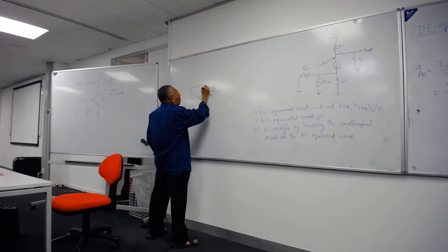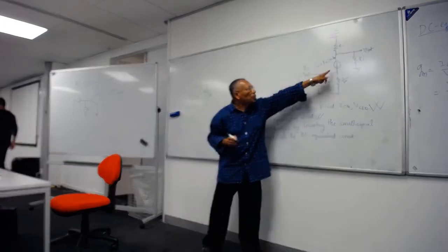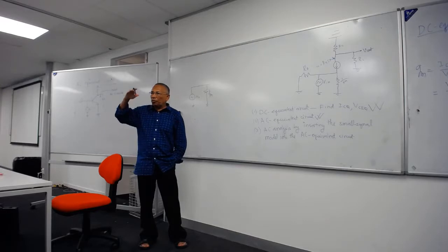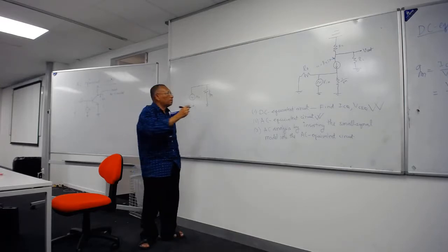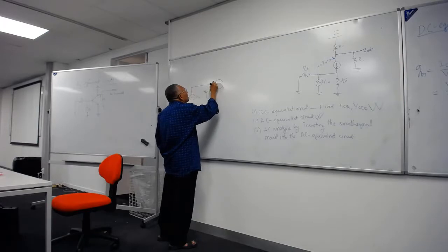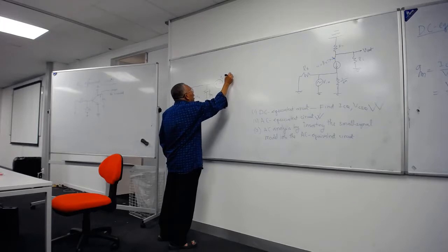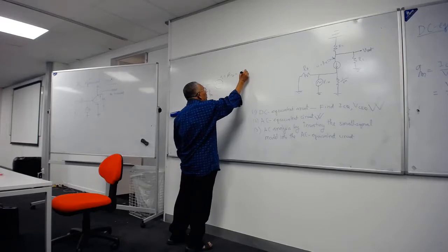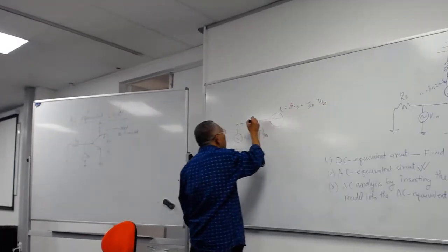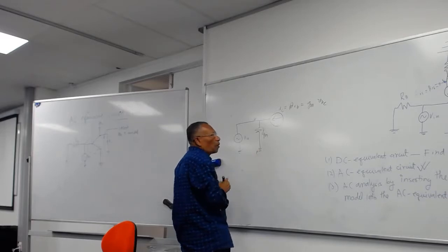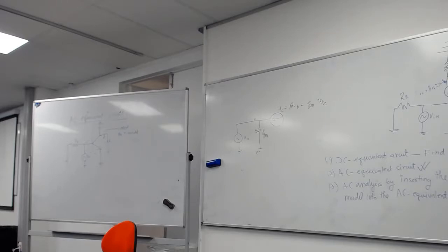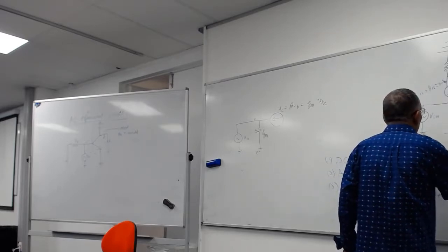And then at that point you have a current source. So you just put this current source. It's better to make it flat, it looks a bit simpler. This is your IC equal to beta IB equal to your GM into VB. This is your base. This is your emitter here, grounded. The emitter is grounded here, both AC and DC ground.